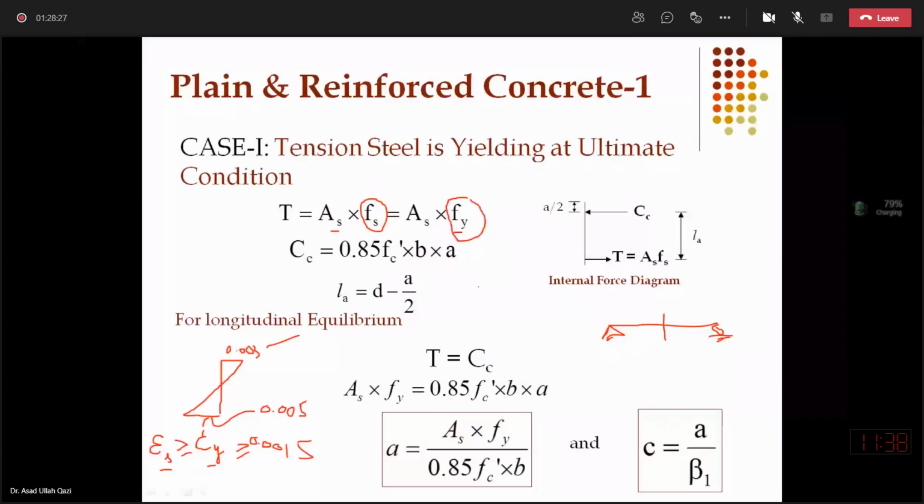So in USD, in terms of steel, we will limit the stress to Fy. Even though my strain is over here or over here or over here, I will only use the stress magnitude maximum equal to Fy. The rest is actually like a factor of safety, that I'm not taking into account the strain hardening or more stress limit of the steel bar. So As Fy,